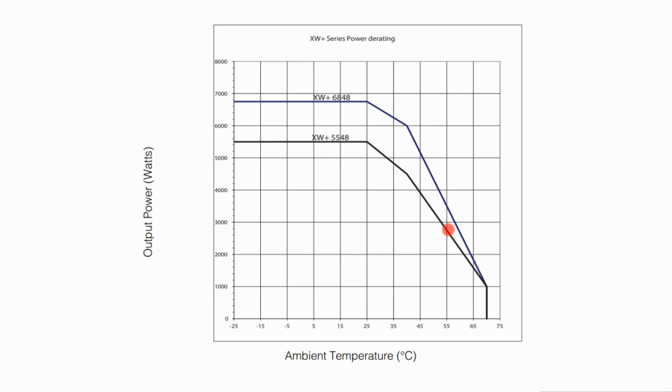I've read about batteries sitting on freezing cold slabs, and the temperature differential across the bottom to the top of the battery can lead to early cell degradation. So I think it's just wise to provide as much temperature regulation as you can, not because of necessity, but because of performance.